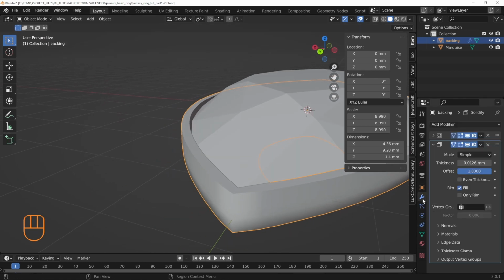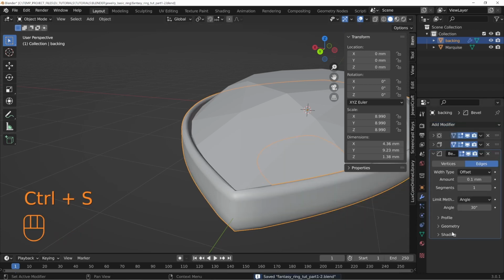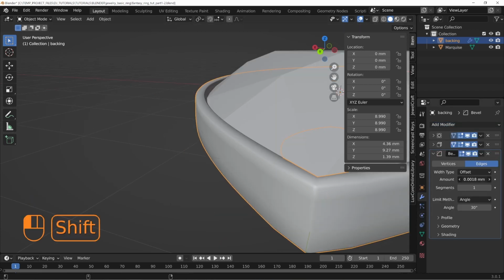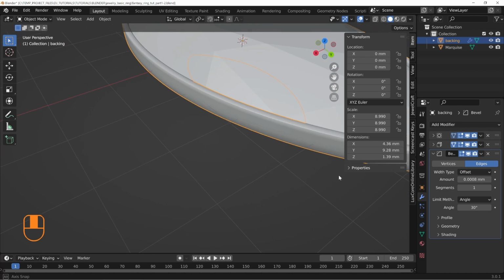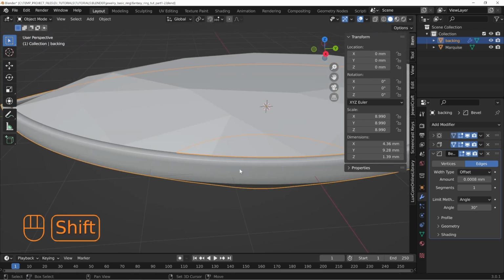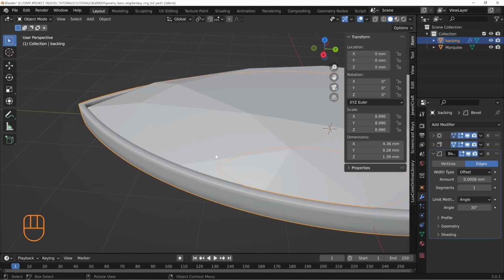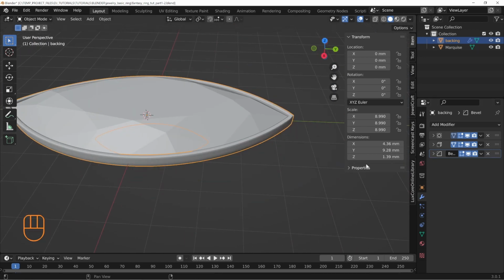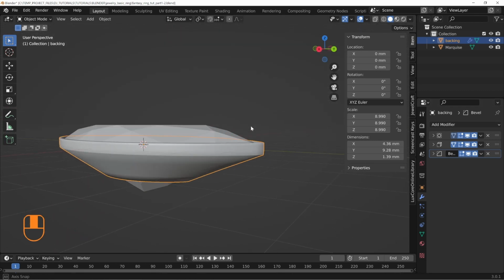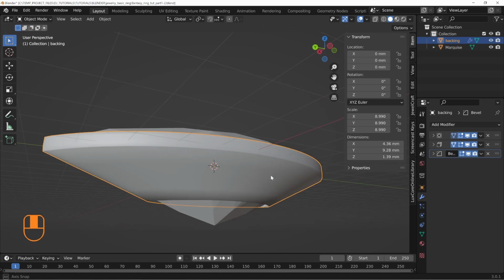And we're also going to add a bevel modifier. Let's just take this amount here and control that bevel shape kind of like that. You can control the angle here to get what you want, but that seems okie dokie, at least for the time being. And I like to model things like this with these non-destructive methods that are this small because we might want to adjust this at some point, and this just makes it a lot easier.